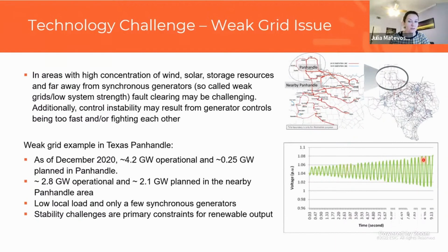And this is actually without any disturbance even happening. This is just power from the plant fluctuating, and because it's a very weak grid and there is no strong voltage source, voltage is very sensitive to any change in current injection into the grid.